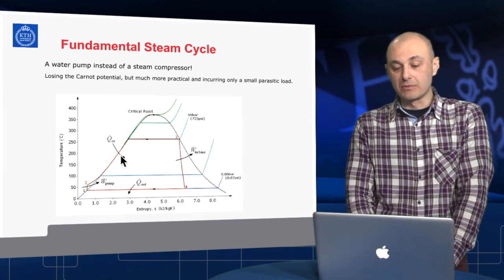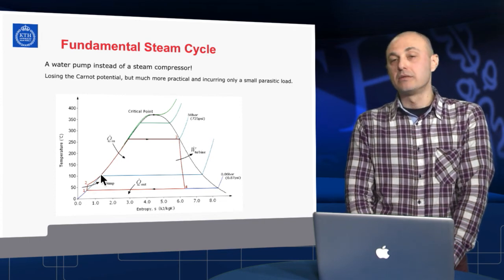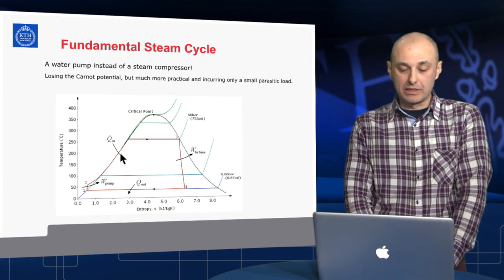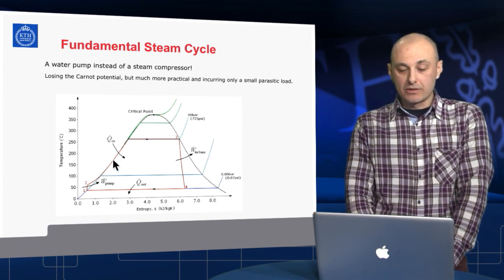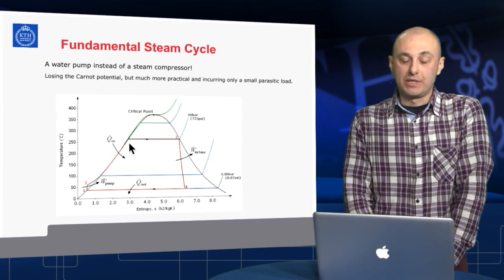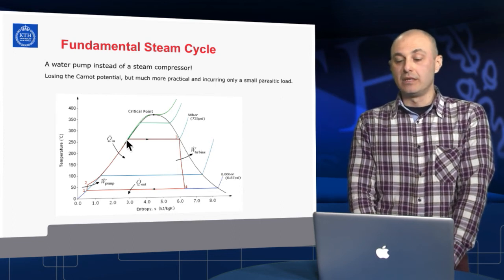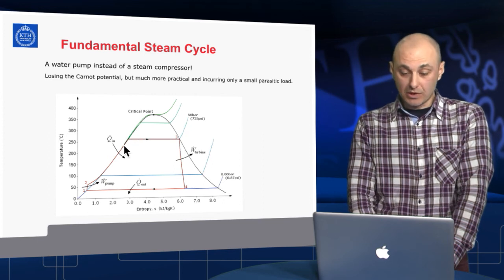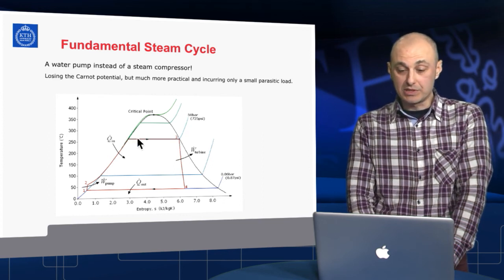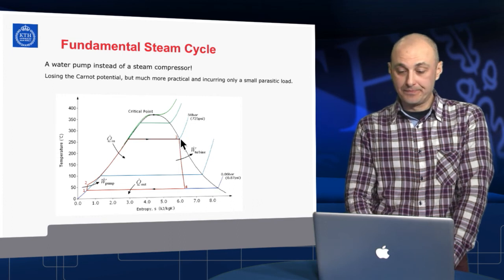Then heating up the liquid water along the constant pressure line in the ideal case, and sliding along also the saturated water line until it starts boiling, defined by the pressure. So this goes along the constant pressure line, which is drawn exactly in this way.